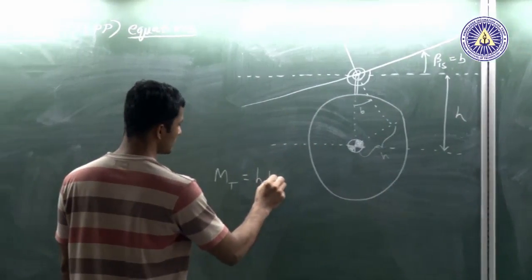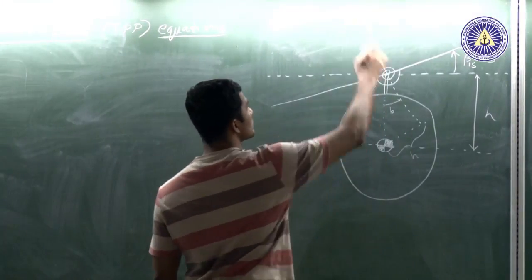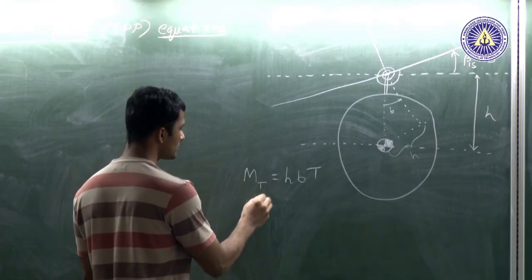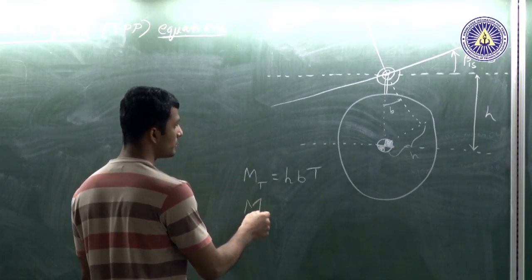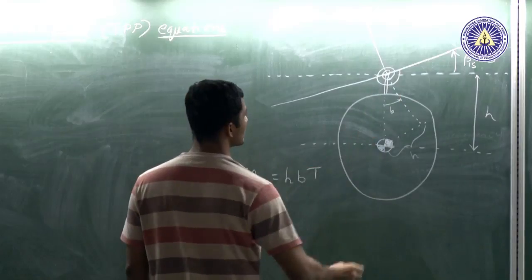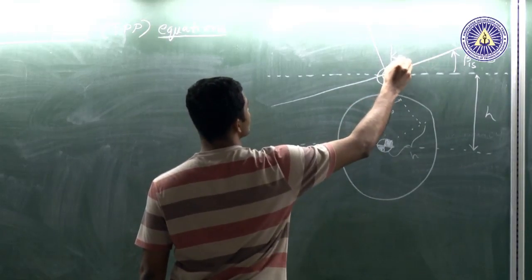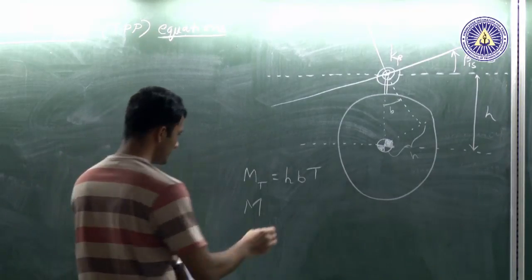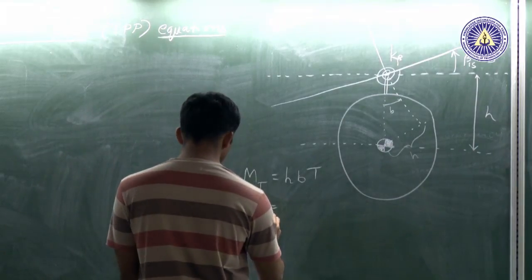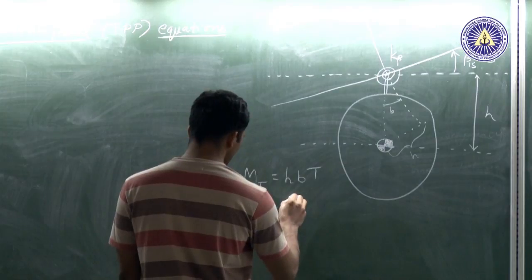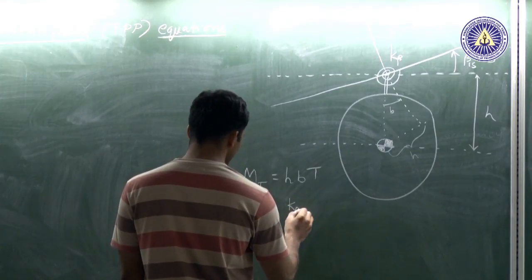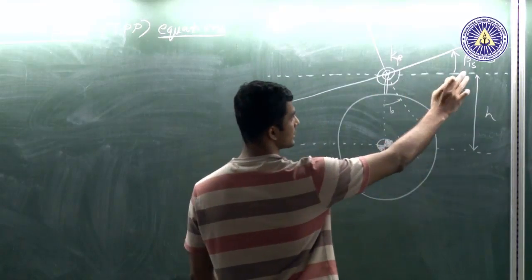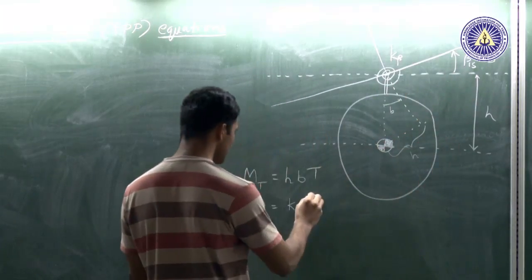So this is hb into this force, which is T, and you have also the moment due to the spring. So spring stiffness is k beta, and that is simply k into beta. So beta at this azimuthal location is beta 1s, which I am calling b.